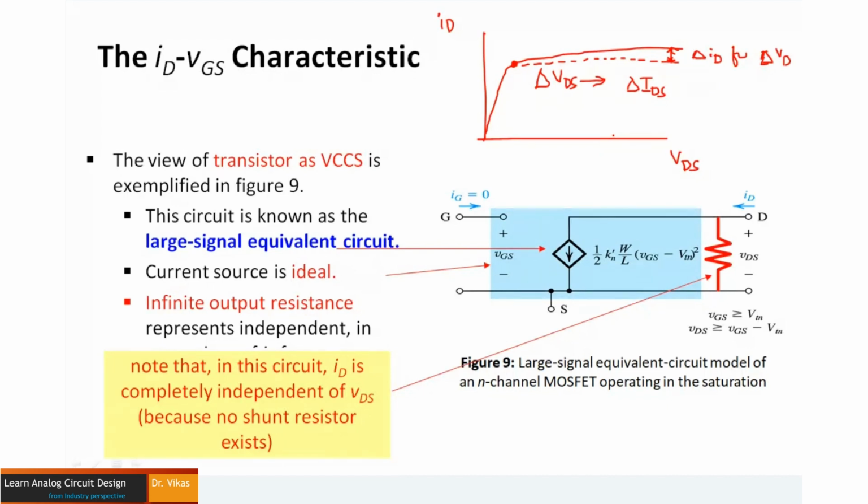But if you observe, there is even a resistance observed in the linear region also. See here, the current is not rising very smoothly. How do we say that the resistance is zero? Whenever you apply a voltage, if the current ideally increases like this, very quickly, then it is the ideal value with a resistance of zero. But if the graph is tilting, that means there is some sort of resistance observed. So even in the linear region there is a resistance, which is represented as RDS, which we saw in the earlier session.